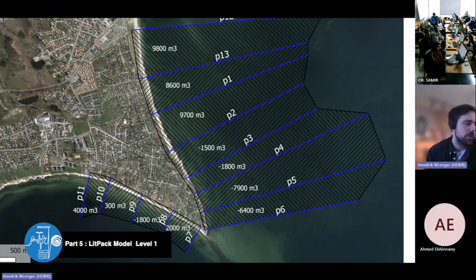And the distance between those structures should be such that the longshore transport can re-establish again, so that, for the groins, you have a local disturbance of the longshore transport. That is not the case here because we have so many structures. So the alternative is that instead of